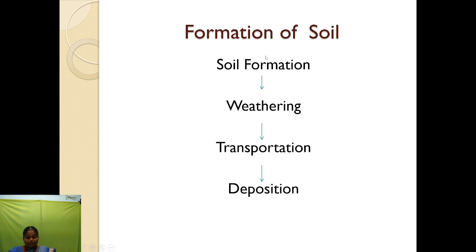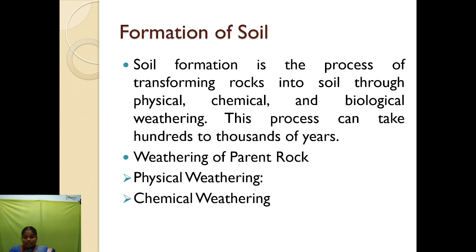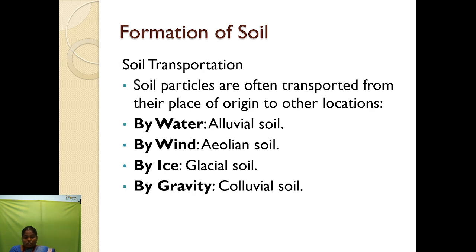Weathering, transportation, deposition: the product of rock weathering, up to the size of gravel or coarse soil, may be residual or transported. Residual soil remains in place directly over the rock from which it was formed. Transported soil is removed from the original bedrock and redeposited somewhere. Transported soil is further classified as marine deposit, glacial deposit, lacustrine deposit, and alluvial deposit.